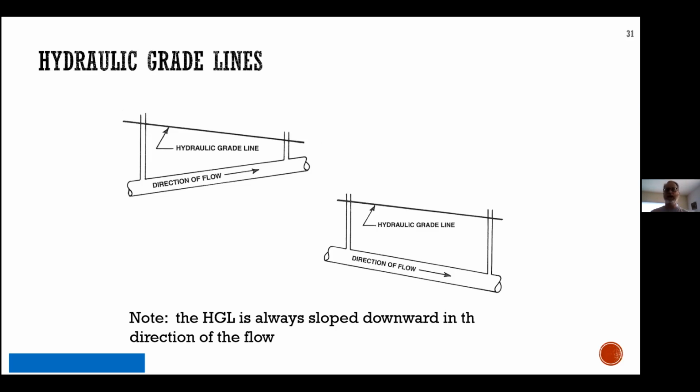So we might have to build an elevated water tower or a pump in order to bring that grade line up. Now the grade line is still sloping away, but as soon as the pump enters the system, the grade line jumps and then slopes away again. But it may be sufficiently high or boosted pressure in elevation to guarantee adequate supply.